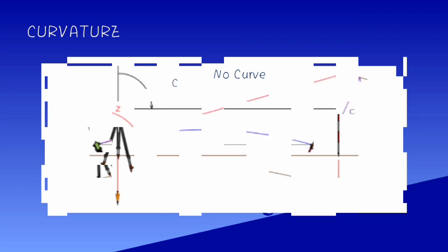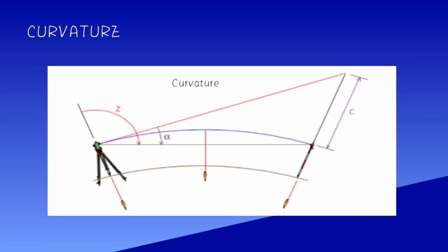As distances get longer, directions of gravity begin to converge, which makes the reference surface curve. The single horizontal black line between instrument and target in the figure separates into three different lines. The red line is the original line of sight at the 90-degree zenith angle.